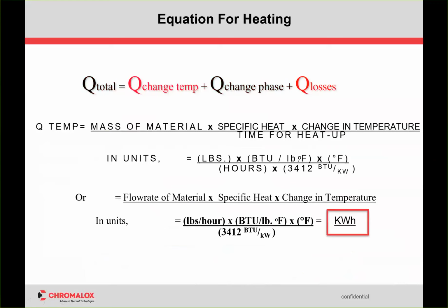What I would point out, though, in thermal input, the kilowatt ratings in all of our products and catalogs are based off kilowatt hours. That is the thermal input over an hour. So the heat up time becomes a topic of discussion, and you should have that discussion with all your customers. How long do you have to do this? We have some calculators, and I'm going to review a little bit how to understand them.